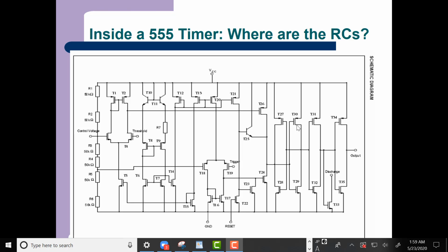The other thing is that on gain stages, you'll have a zero. And for that zero, we're going to have to do small signal analysis with a small signal model that we will add capacitors to. So we'll add capacitance to the small signal model, do small signal analysis to figure out where a zero is.